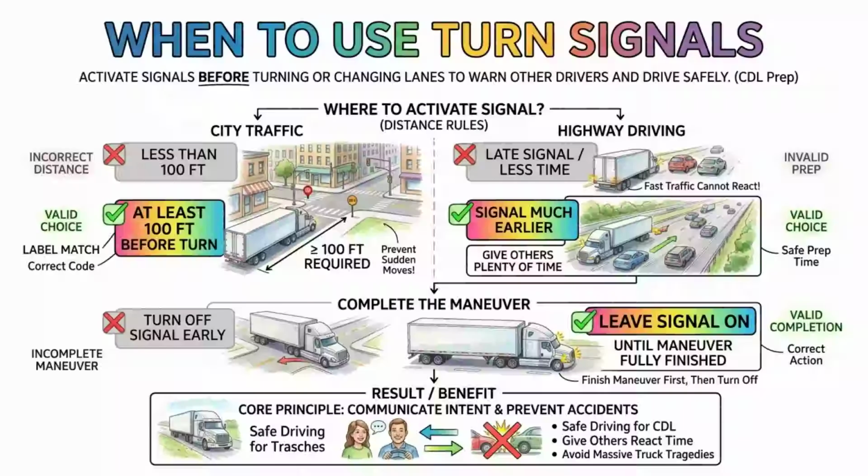Tire safety is critical and has specific tread depth requirements you must memorize. For the front steering tires, the law requires a minimum tread depth of 4/32 of an inch in every major groove. For all other tires on the vehicle, including drive tires and trailer tires, the requirement is only 2/32 of an inch. Additionally, you cannot use recapped or retreaded tires on the front steering axle of a commercial bus or truck. This distinction between steer tires and all other tires is a favorite question among test creators.